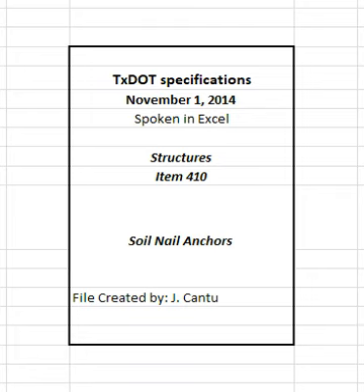List and sizes of excavation equipment. Drill rigs must have an articulating head in a vertical plane, cutting head, auger, rock bit, etc., tools, trimmings, and grouting equipment. Procedures for the sequence for the following items of work: excavations, drilling and grouting, soil nail and wall drainage system installation, and, if appropriate, facing construction.